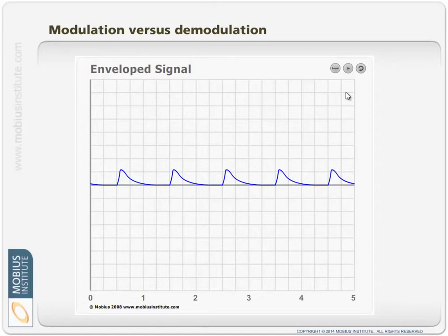So it can be confusing. We can say, well, isn't the signal the same as just the vibration? No, it's not. There's a number of reasons, but really what we're doing is we're taking advantage of the fact that the bearing resonates, or the sensor resonates, or we can pick up the stress waves. We can use some signal processing to detect those very short duration peaks or impacts, whatever you want to call them, and then going through this so-called demodulation process, we make them visible in a spectrum or a time waveform.